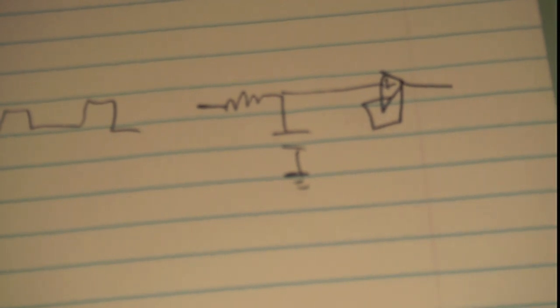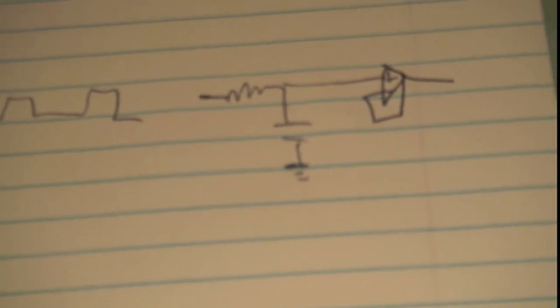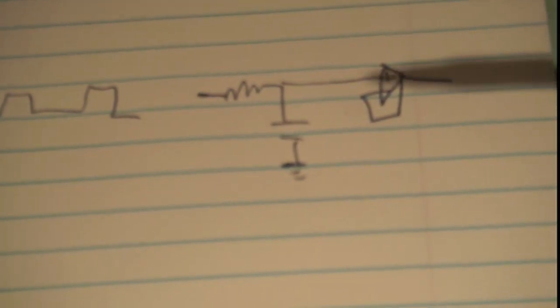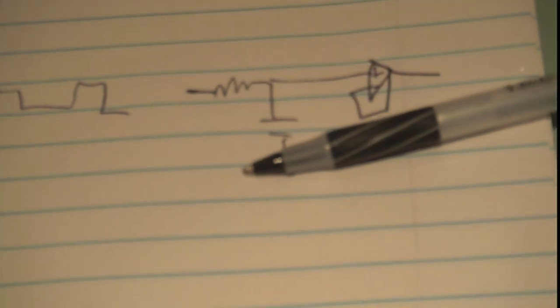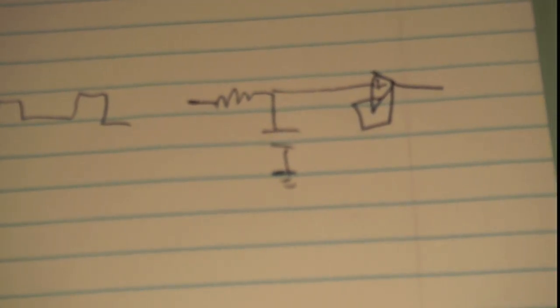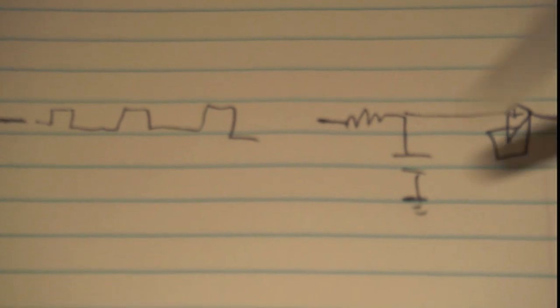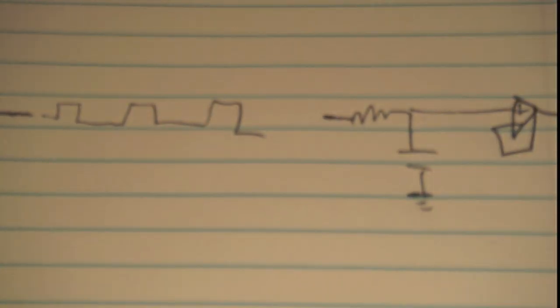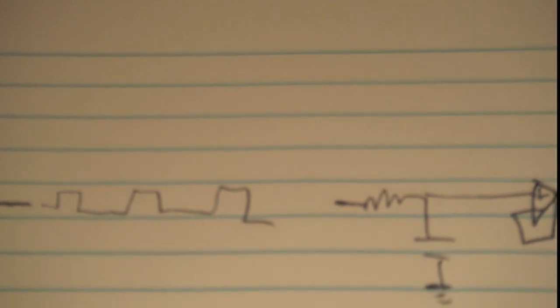First off, what is an RC filter? You've probably heard of RC, LRC, and stuff like that. Those letters just denote what the filter is made of: R for resistor, C for capacitor. So that's what that is. Second, what does low pass mean? I've been talking about an RC low-pass filter on this PWM signal. A low-pass filter essentially blocks high frequencies. So a low-pass filter is a high-block filter, meaning it's going to block high frequencies.